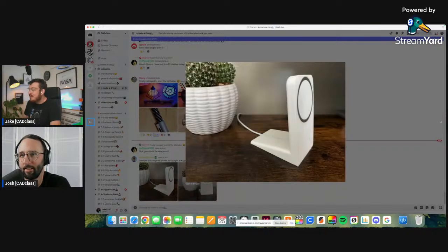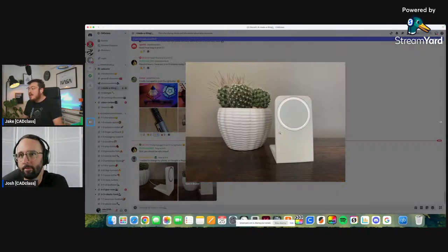I love this stuff. By the way, really good design or printing orientation by printed by John. If you want to show off a part of your 3D print that tricks people into thinking that it hasn't been 3D printed, have the build plate surface be the showcase side. If you can kind of see from the lighting, it's got a rough texture on it, which looks exactly like a rough texture plastic injection molded part.